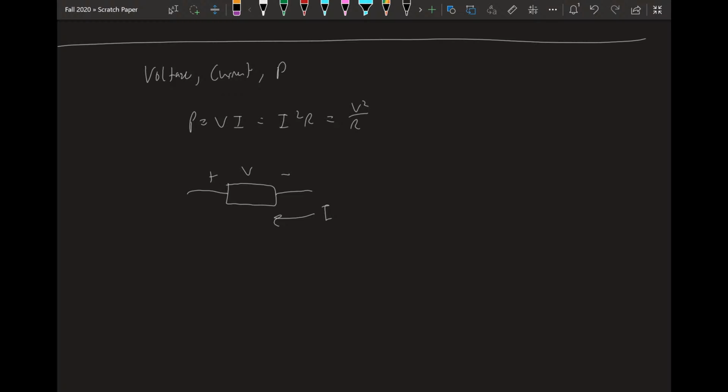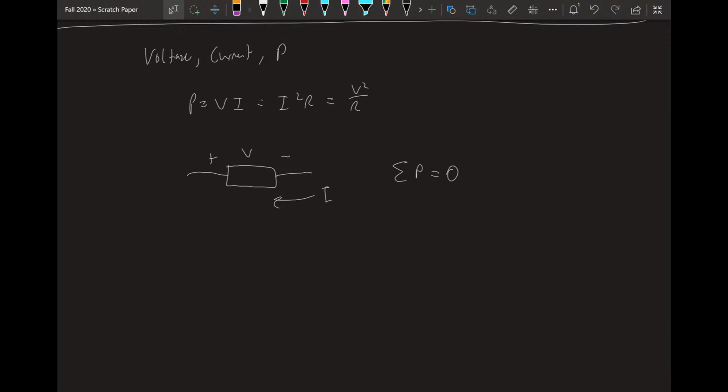What does this negative and positive power mean? In these linear circuits, power is conserved, which means the sum of power equals 0. Resistors will always absorb power, and absorbing power relates to positive power. Negative power means you are delivering power to the circuit, in the form of circuit elements such as voltage sources and current sources. Although sources don't always have to give power; sources can absorb power too. But resistors cannot give power. They have to absorb it only.